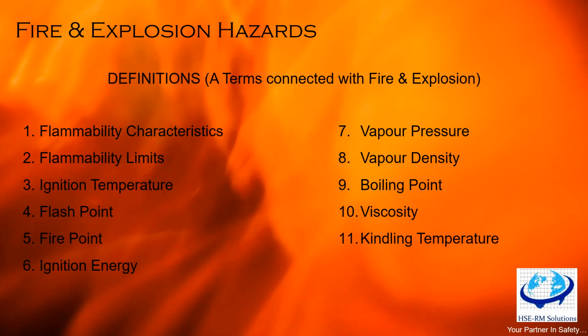The minimum energy usually occurs close to the stoichiometric mixture, something like that. So that's what it's all about. It is not that the electrical spark is happening somewhere and the fumes are generating somewhere else. It has to happen very closely. Only then will ignition happen.